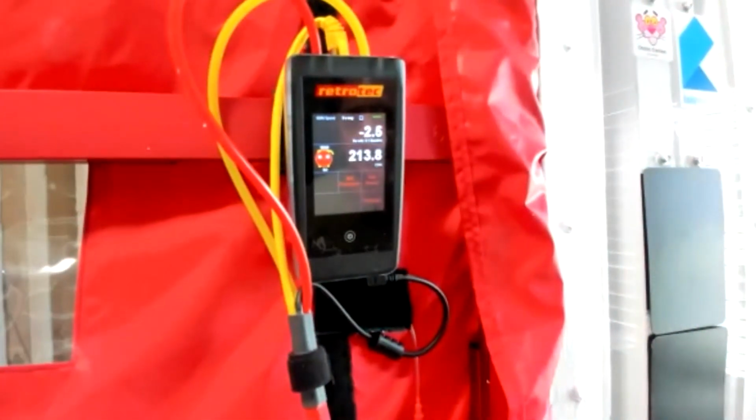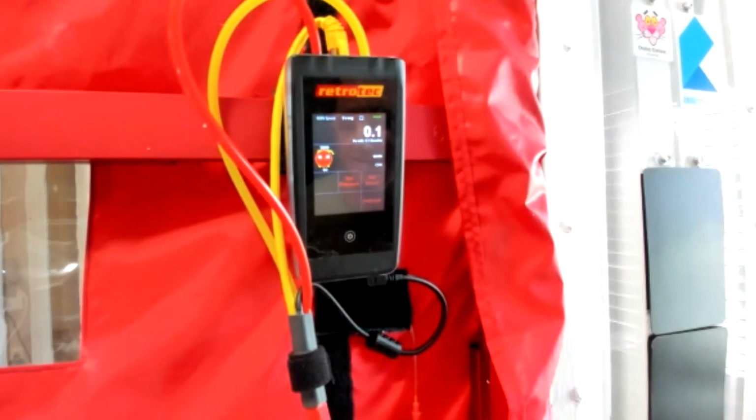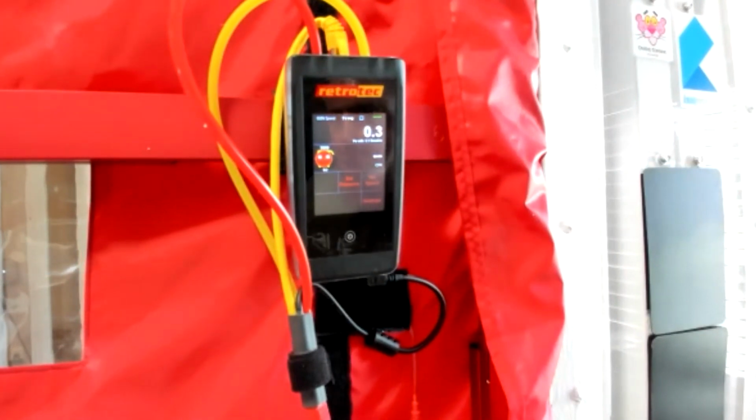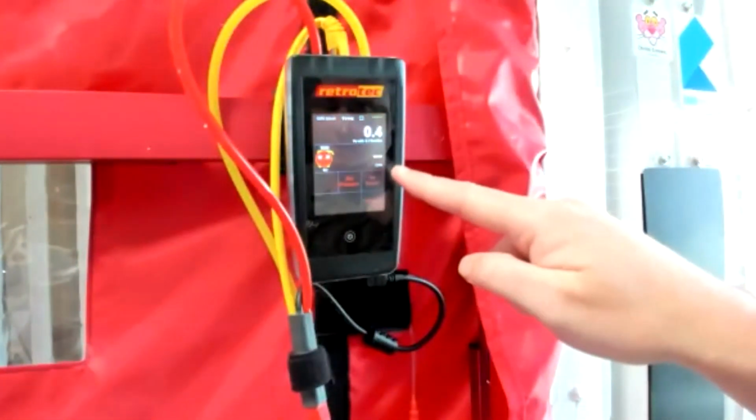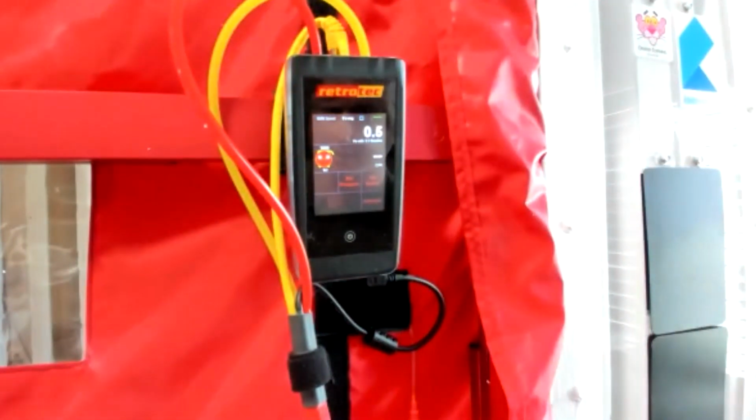So that's when the gauge is telling us, hey, I'm going as fast as I can and I can't get to 50, open it up. So if you can't get to 50, open the fan up. If you can get to 50 and you're getting these 2 dashes, choke it off some more. That's how the gauge tells you which range you need to be using to get the reading that you need.